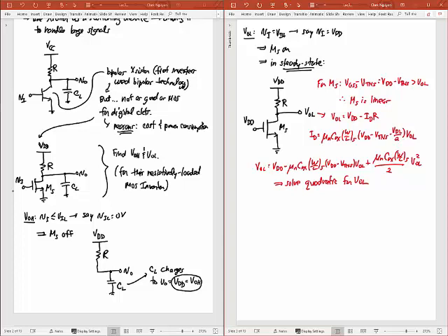And so I can write an expression for I sub D because I know the linear expression for I sub D, and this is it right here, with VDD as the input and with VOL as the VDS, which I'm showing there. In the last lecture, I think I'd written VDD right here. That was wrong. This should be VOL right here, sorry, for output low.